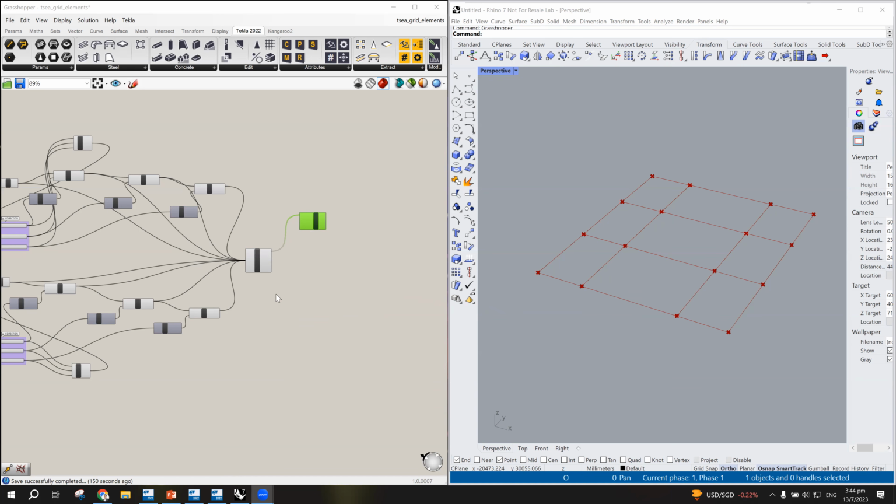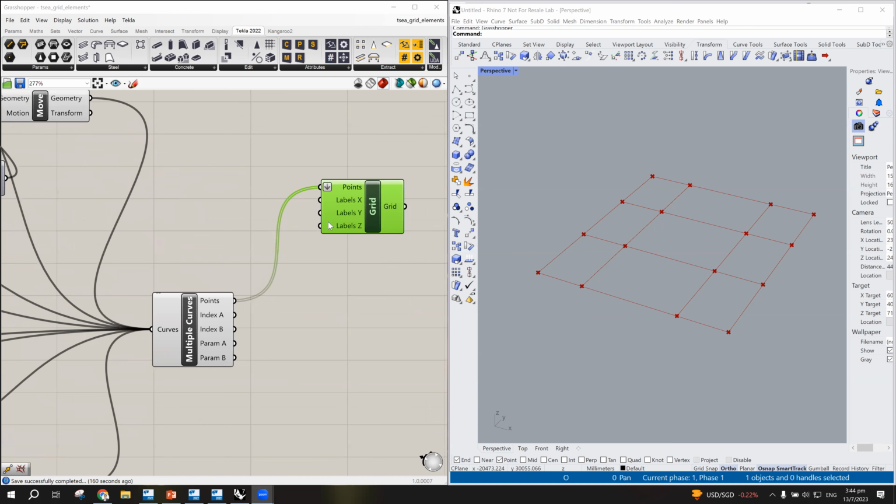How to disconnect the link? Okay, to disconnect the link, you can just simply look at my cursor, right click on the point and then here disconnect this one. Or if you don't want to do that, then select this one, press the control key and then put it like this.